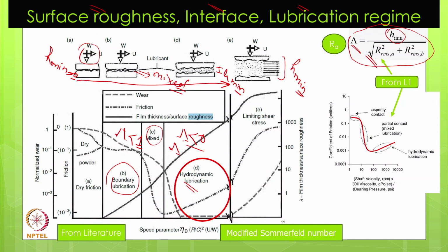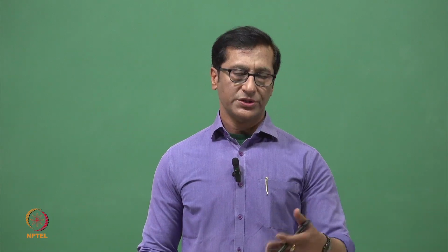Of course, if there is a complete separation, then hydrodynamic lubrication will come. I believe that generally when it is greater than 2 or 3, hydrodynamic lubrication may come. Of course, it depends on the situation and the conditions.